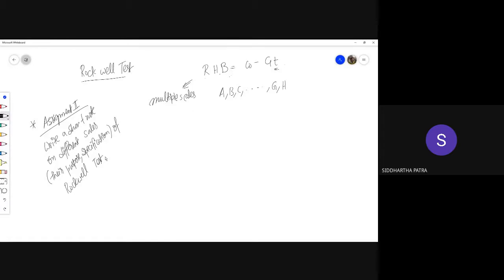Now these scales are meant for materials of different hardness ranges. So if I take scale A, that can measure hardness for a given set of materials. For our experiment, Rockwell B scale would be used. That is the most suitable scale. So you can group different types of materials for a given scale. So a given scale is suitable for only a given set of materials.